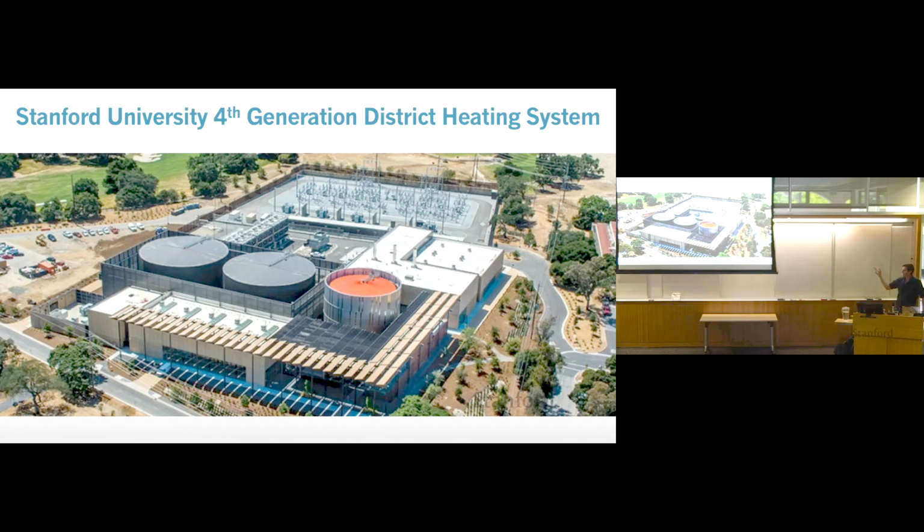And so there are 2 chillers and a boiler. There are about 35 miles of cold water pipes and about 40 miles of hot water pipes around the university, because at any given time, different buildings need either hot or cold water or air. And so the hot and cold water are stored and produced in these boilers and chillers. There are heat pumps, electric heat pumps used to raise the temperature of the heat or to lower the temperature of the cold, where the electricity comes from the solar.